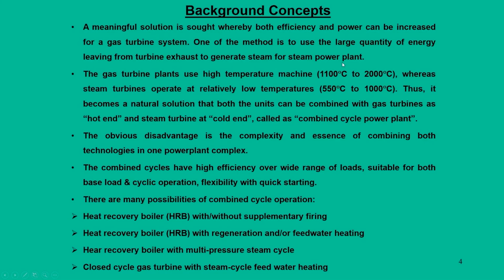Normally, a heat exchanger is one way gas turbines are operated in non-ideal mode, which we call a heat exchange cycle. But instead of a heat exchanger, the exhaust from the gas turbine can be directly coupled to provide the necessary heat input for a steam power system.